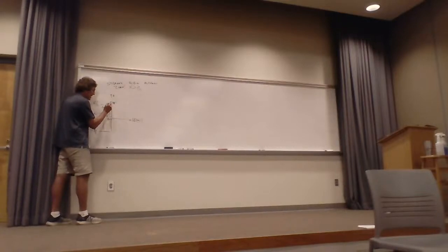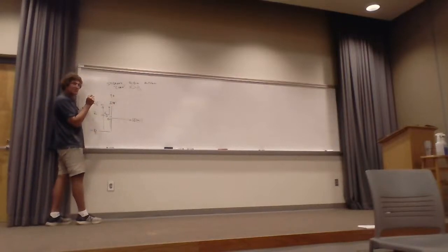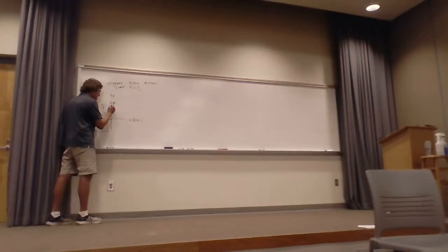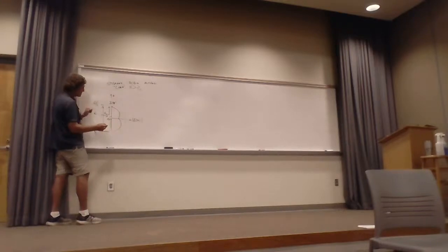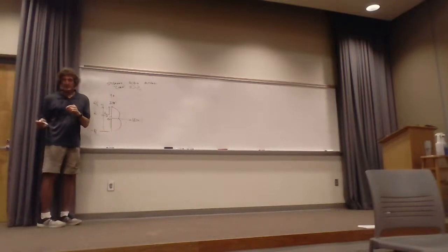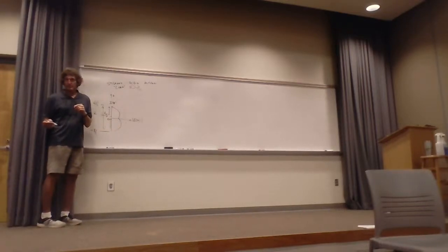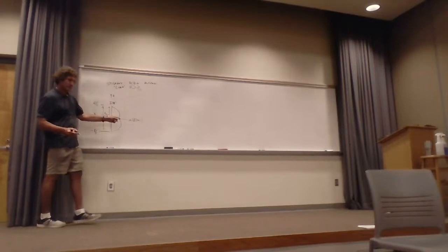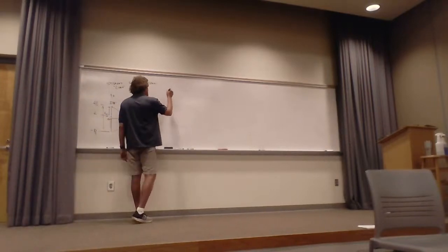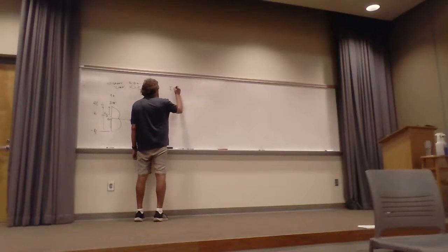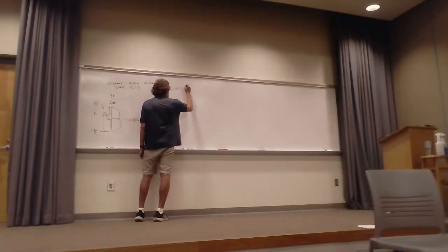What you'll see is the current has to go to 0 at the ends, because this is a real antenna. Now, it has to go to 0 at the end, and we'll have something like this. You don't know if it's a maximum at the center or not, but it'll be symmetric about the center. Do y'all follow me? The formula for this, I of Z, is given in the book, and it's I naught.